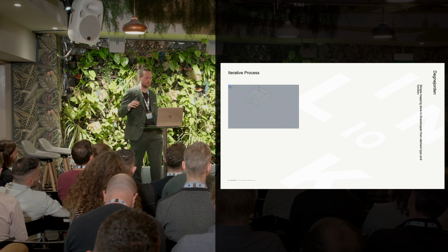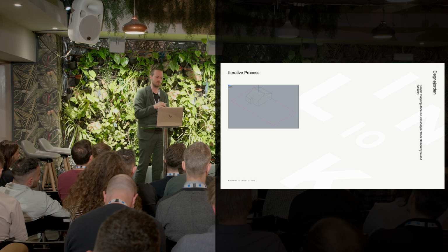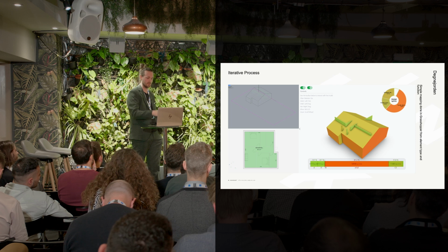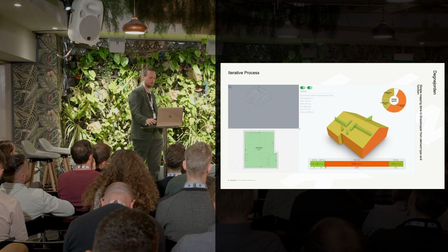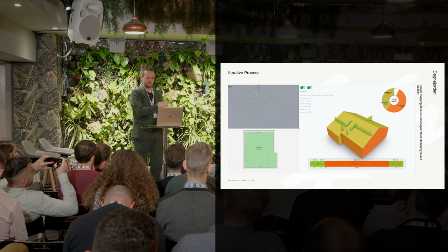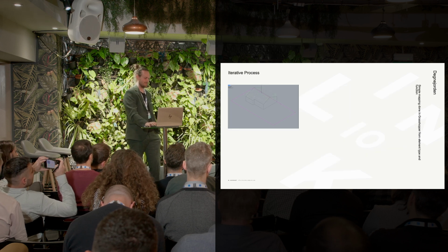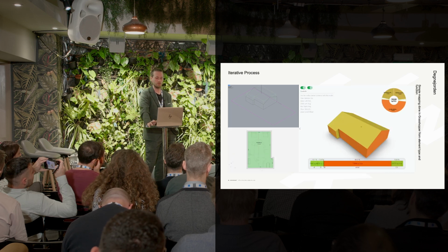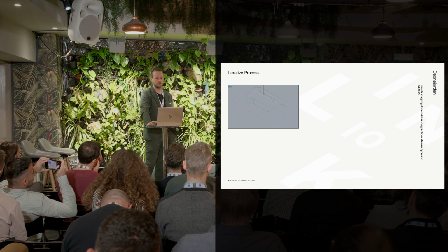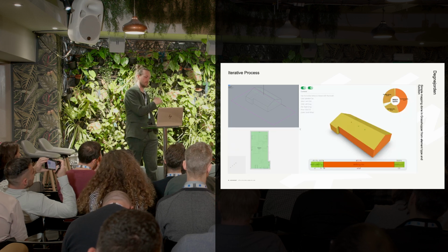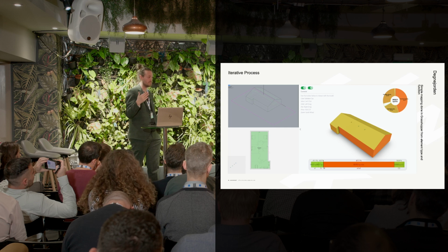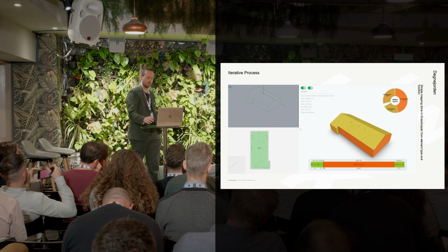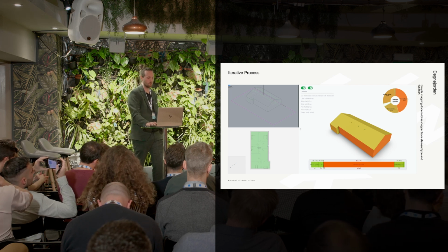We start to extrude this model. It's a very simplistic modeling setup, but we extrude it, we generate a new plan, we get our new dummy values, we send all of this information, and we map it. And then it's AI, so walls are sticking out of the roof, that happens, but we continue with the same process: you change your model, you get your AI plan, you do your mapping. This is to integrate the structure and show that you can really push it and make quick changes. Since the Speckle send is very fast, you can just do your modeling, apply whatever process you need, and then through Grasshopper send the geometry.